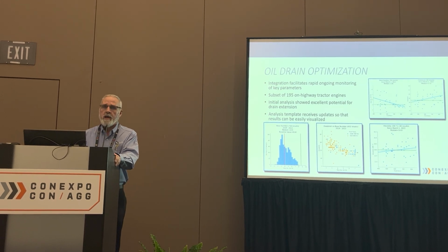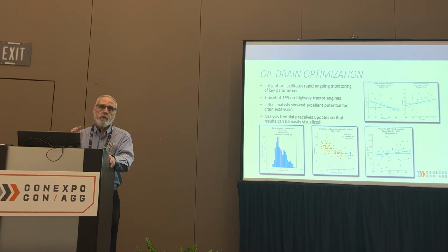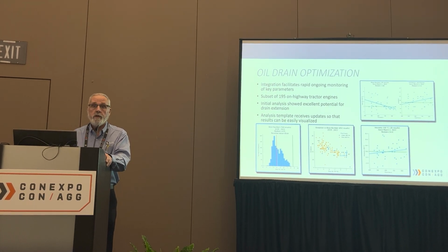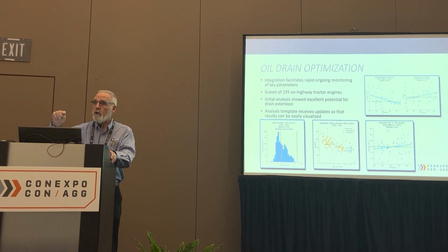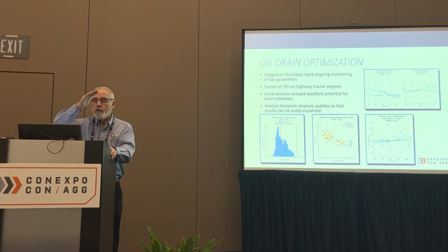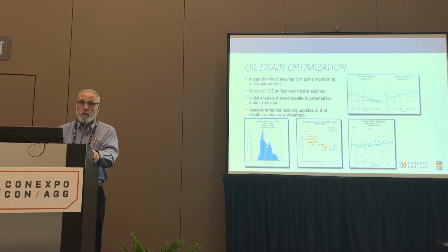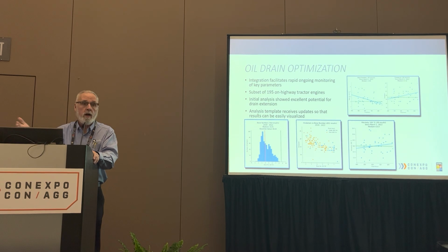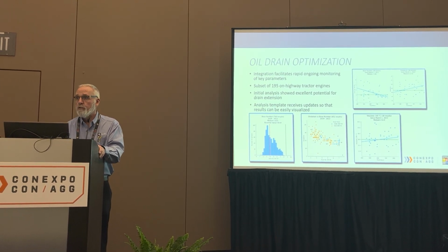time. And scatter plots are just absolutely terrific to say, all right, I just want to look at my QSK60 engines. I'm comparing viscosity versus hours on the oil, and just follow that down and see, at 500 hours, or maybe we can go to 750 hours based on the sample results, and feel really good about extending that drain